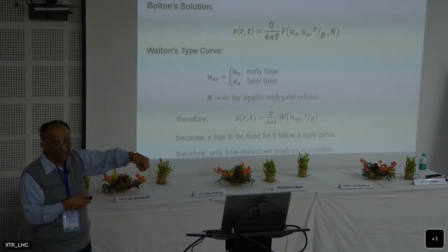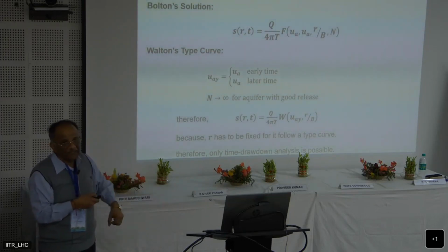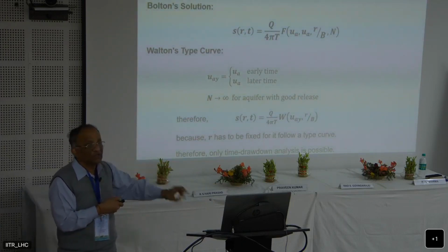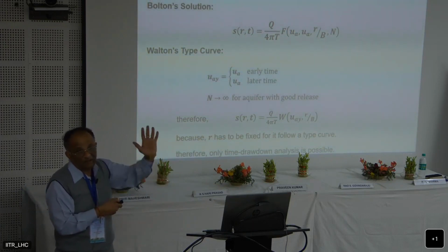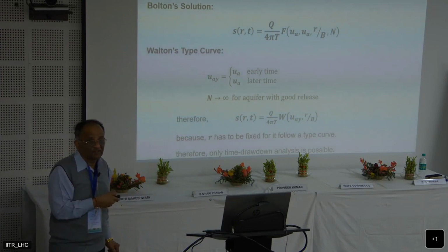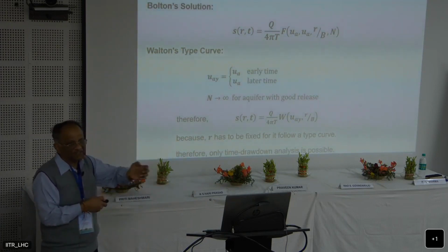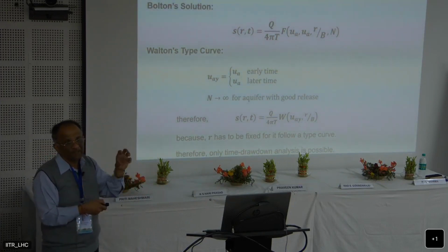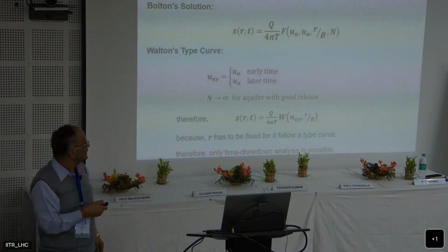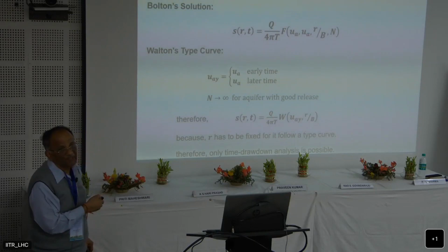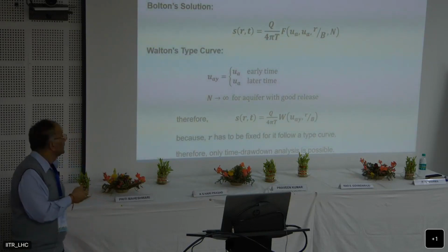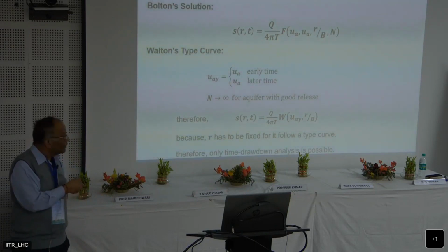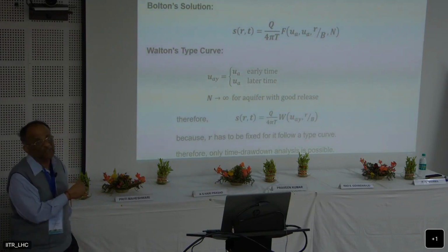That means if I pump a well in a clay material, the time required for it to totally drain is 4 or 5 days. Basically it will be sending water out of storage very gradually. It will not become dry very fast. So that alpha, or 1 by alpha, is also an important factor. To get this alpha from the pumping test analysis, you have to run it for a considerably long time.